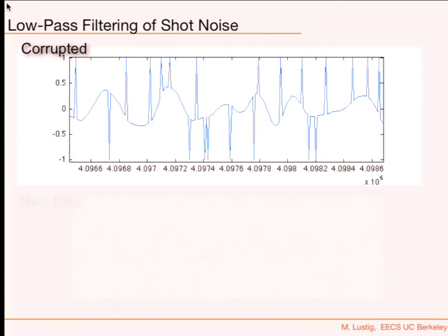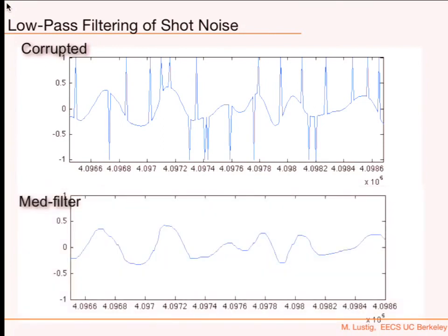If I do a median filter, look, it's just beautiful. It recovers this so beautifully. It gets rid of all the noise. It's really good at removing what's called salt and pepper type of corruption in images, for example, which is black and white pixels. Actually, all your cameras have white pixels on the sensors. A lot of ways to deal with white pixels is some median filtering or some type of operations in cameras as well that do exactly this.